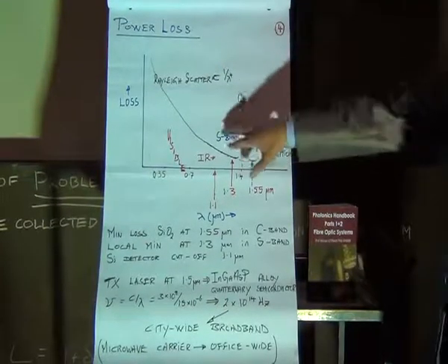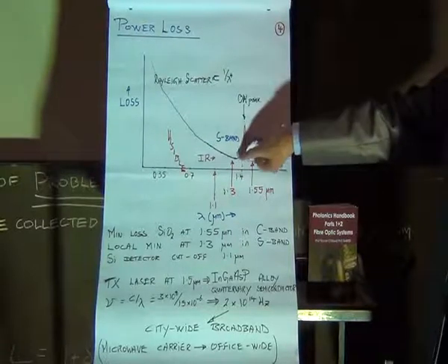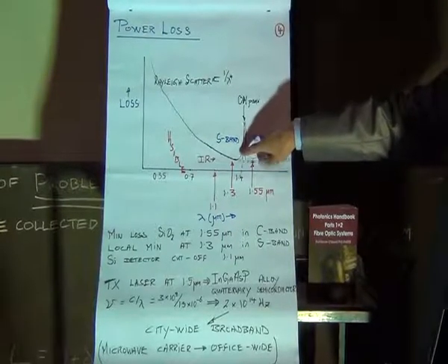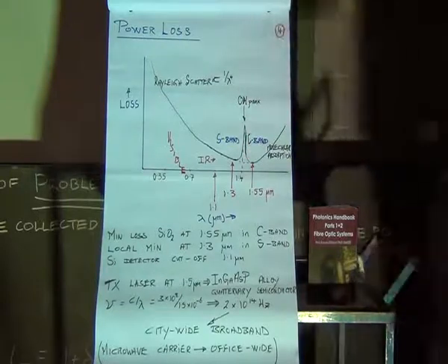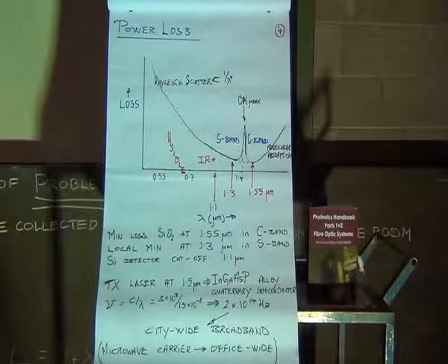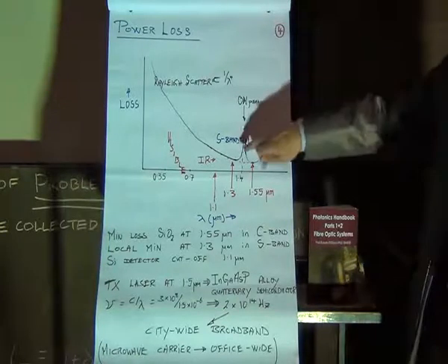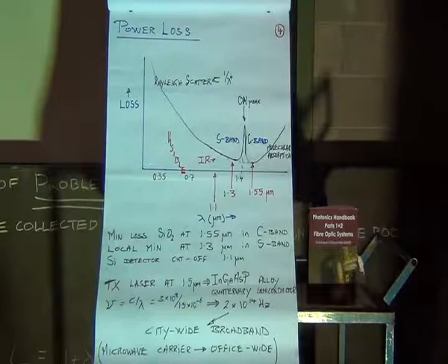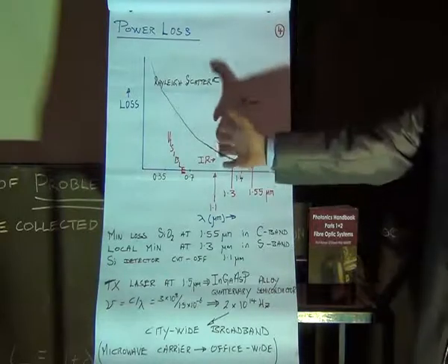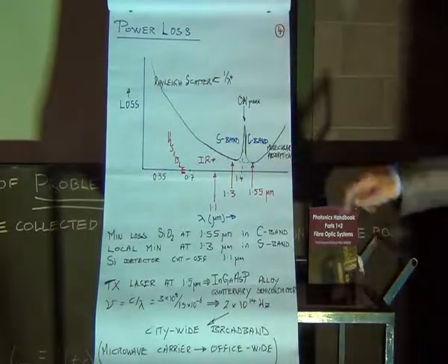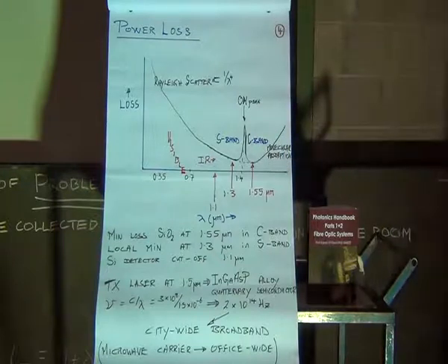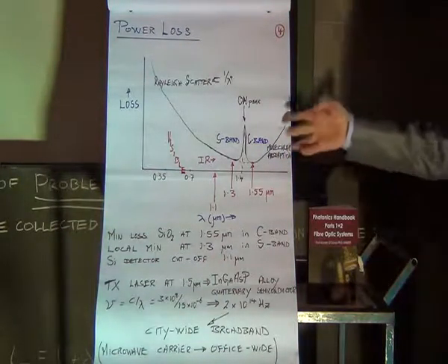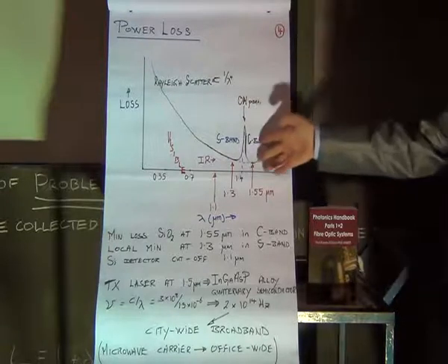Now it turns out, apart from those two processes I talked of, you can never get rid of all of the water. There's always a small bit of contamination. Those carrier gases, it only takes a few molecules per billion, and there's enough water left for the OH bond to vibrate. And that causes a peak absorption around 1.4. So the water peak separates the S band, what we call the short band, from the C band, or conventional band. All your telecom systems today operate here.